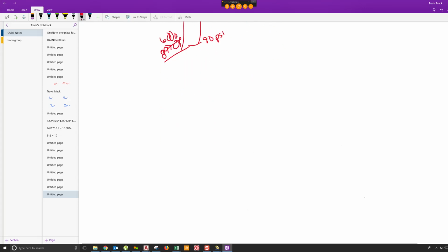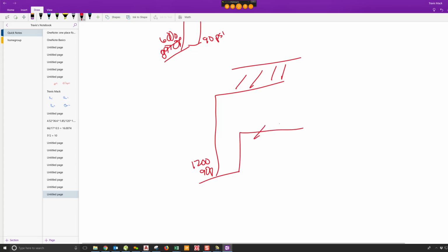Or let's say it's just reversed, as I've got a manifold here go up, have my grid system this way. Say I'm doing some crazy ESFR system that has in-racks with it. It's something crazy. You know, I've got 90 pounds here at 1,200 gallons, and then I've got to have some rack system here. Well, if I calculate my rack system with the way that I first calculated it, say it's only 50 psi